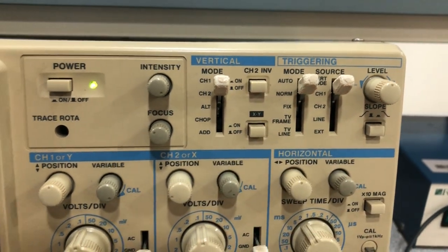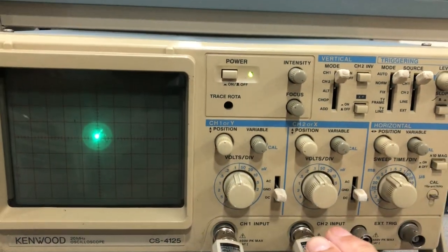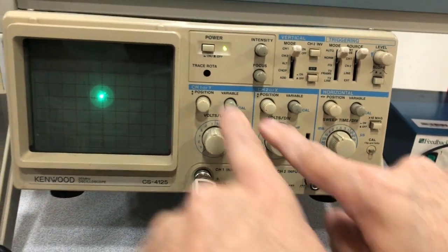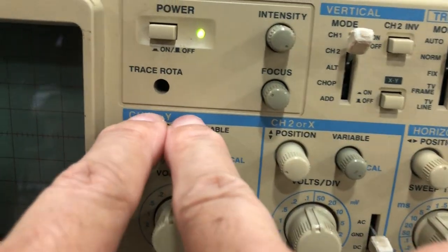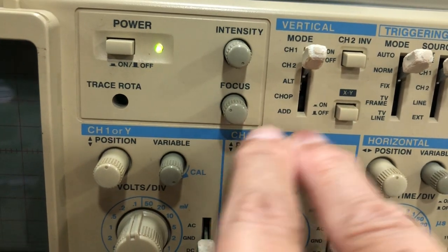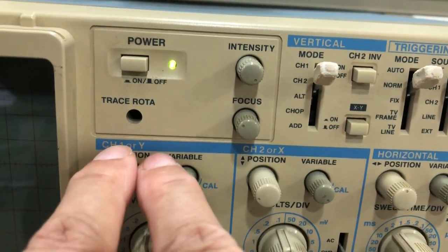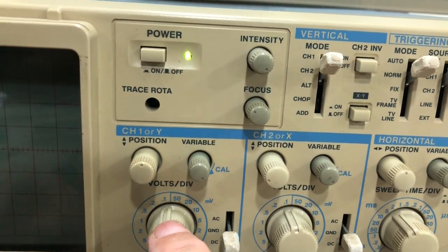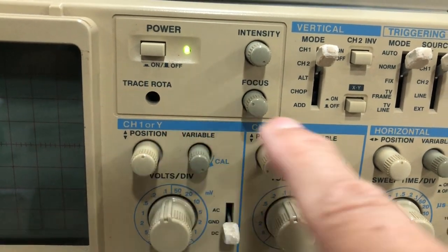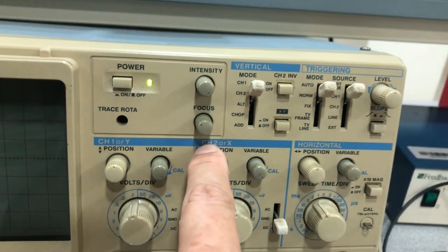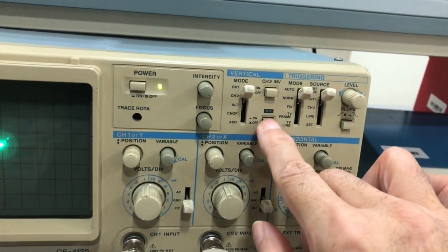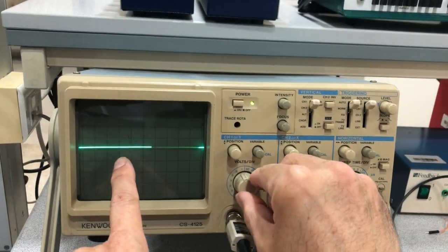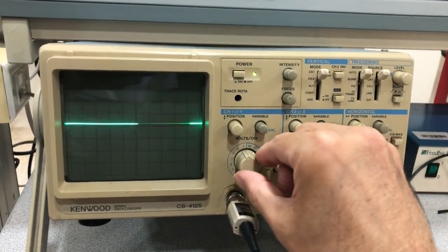I'm plotting this voltage of channel 1 against this voltage of channel 2. Notice here they named it Y, although I had named the first one channel 1 X and the second Y, but it depends on the plot. Maybe this channel raises the beam upward, so they named it Y, and this channel moves the beam horizontally, so they named it X. So we're not going to learn XY today, so I had to turn off this XY. Now I see my horizontal line, okay?